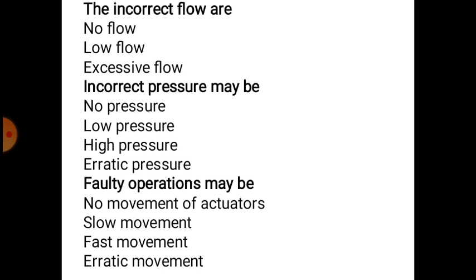Excessive fluid flow may be due to flow control valve set too high, so you must adjust the correct flow by flow control valves. Motor driving at higher speeds: due to high speed of the motor, excessive flow of the oil will take place, so replace the motor or reduce the speed of the motor. Improper pump size: replace with correct size pump.